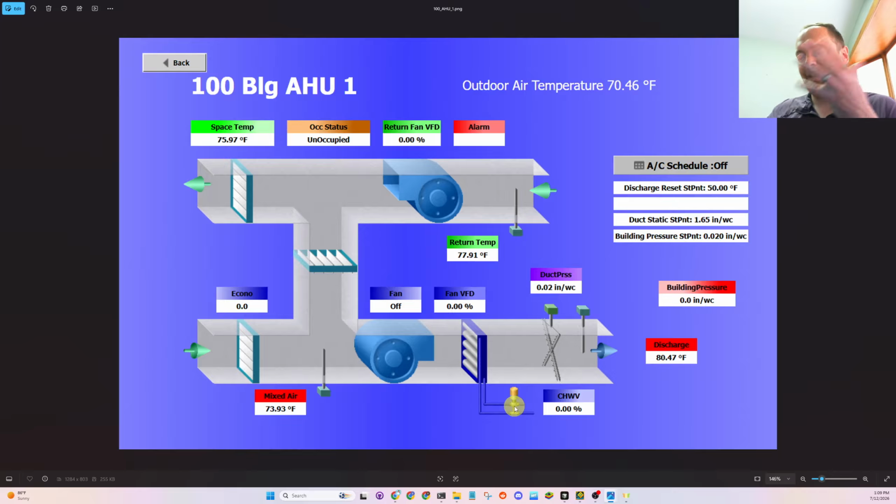They had all these contaminants in the chilled water system, and the story is that there were so many contaminants that it acted like a sandblaster on some of these old valve stems, and it slowly caused the valve to no longer have a seal. So when the pumping system pumps, the valve starts leaking chilled water. Sometimes I've even seen where the little actuator on top just dies, and then it's stuck in some fixed position. So that happens too. All right, so hopefully that makes sense.